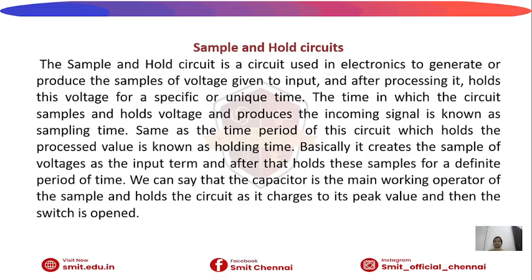So there are two times. One is the sampling time, another one is the holding time. Sampling time means the time in which the circuit samples the voltage and takes the incoming signal. That is called sampling time. Holding time means the time period in which this circuit holds the processed value. This is very important, these are two more questions.